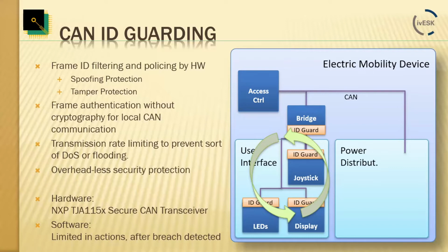For instance, in a software solution, we offer a simple variation where literally this ID guarding task monitors the messages transmitted by this device and then automatically knows, oh, if this device transmitted this ID, we know this is an ID we need to protect. And so this is kind of an automated setup. However, this is not as secure as if it were pre-set up, because if the code here is compromised, then maybe it transmitted data that it shouldn't be transmitting in the first place.